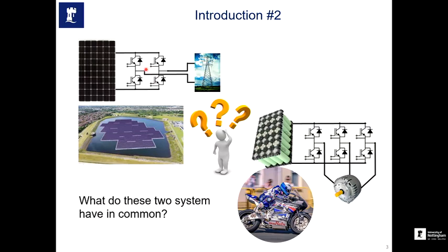the 2 circuit schematics. This one is a single-phase inverter. It's using a PV panel as an input. As I said, it generates DC power, so there will be a DC voltage in here. And whenever we want to connect this to our grid, we need to convert this DC to AC, and we use what we call a full bridge inverter circuit, or a full bridge circuit. Then we convert the DC to AC, which goes to the grid, okay?